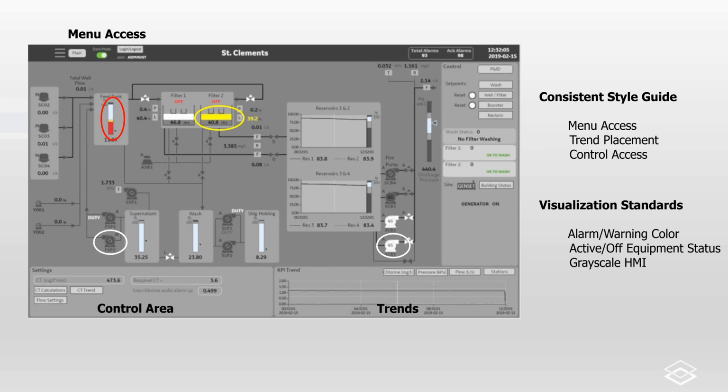They chose to always return back to a home condition and drill down from there to their different levels of navigation. Towards the bottom of the screen, within the process area, you see two things highlighted. There is a pump that is gray and a pump that is white. The pump that is white is active and running. The one that is gray is available, but is not running at this time.